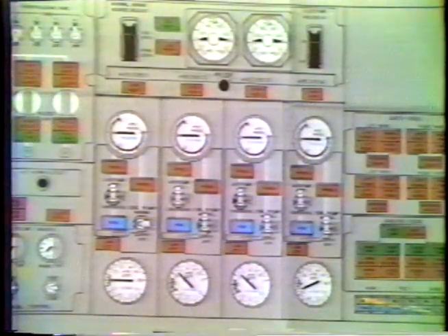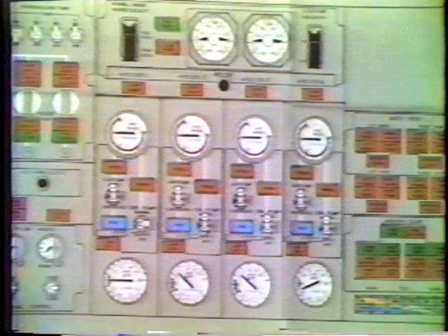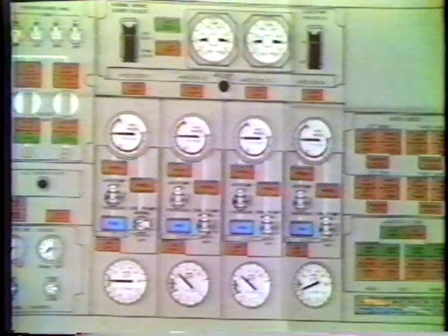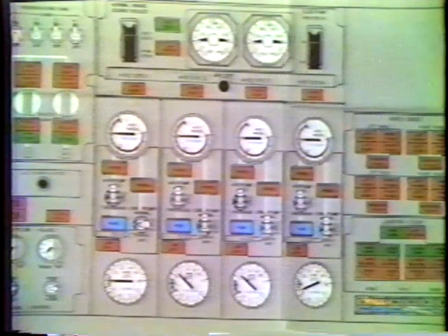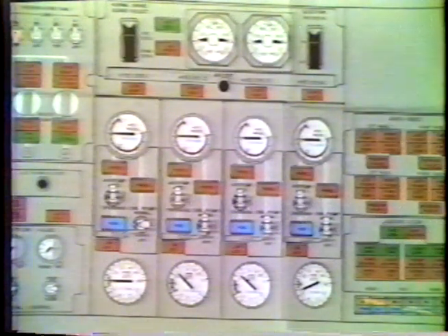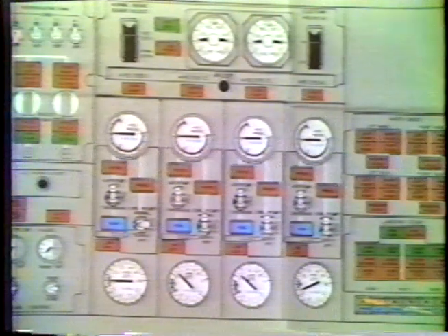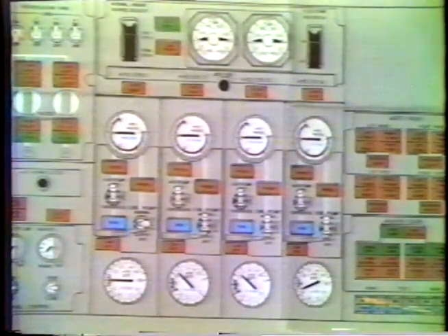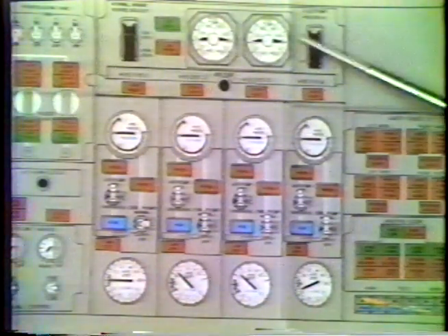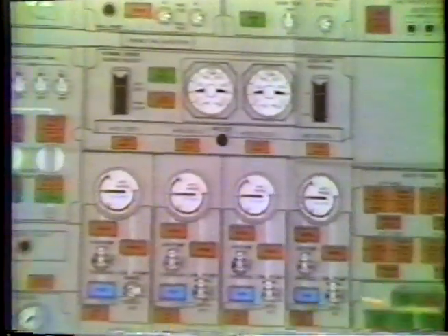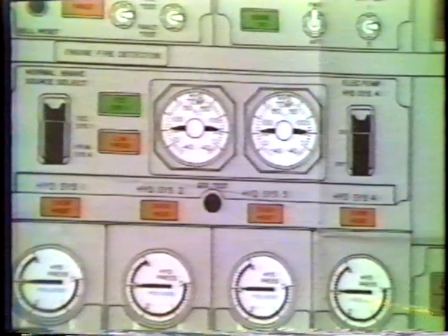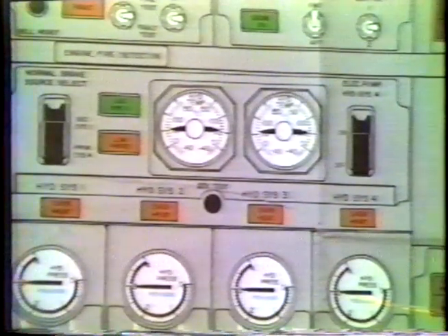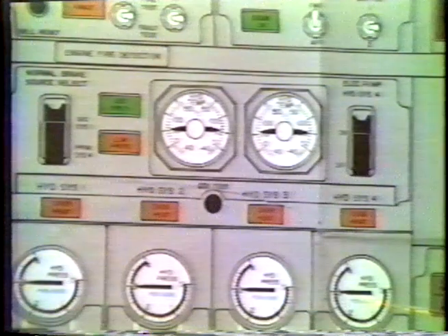Well, what will make that case drain line fluid hot? Potentially, it was excessive leakage in the pump. The pump gets old, it gets worn, and fluid is leaking past at a higher than normal rate, which would heat the fluid up and cause this to read warmer than normal. The normal temperature generally runs around 45 to 55 degrees. When the fluid going past this gets hotter than that, it indicates something is wrong.